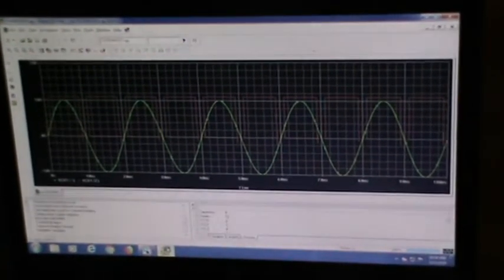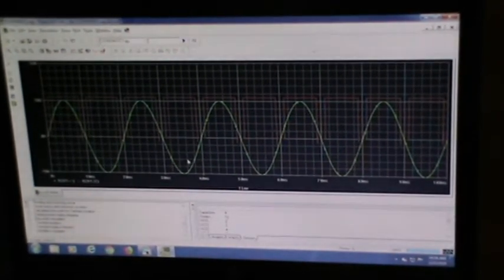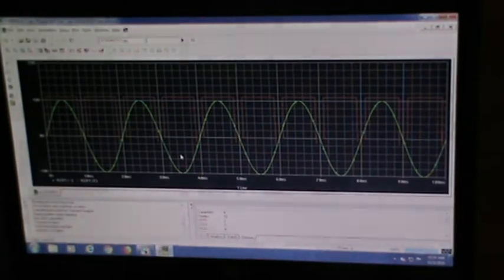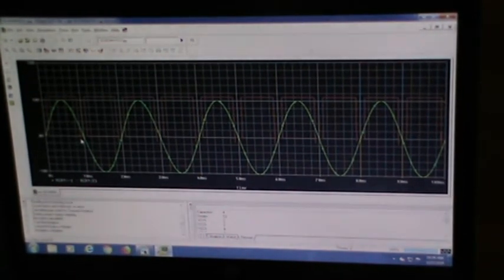Okay, so whatever is coming in green color, that is the input waveform, the sinusoidal waveform that you are giving. Now whatever you are getting in red color, that is your output. So how to analyze this output? What is my LTP and UTP? I have given my LTP and UTP as +3 and -3.